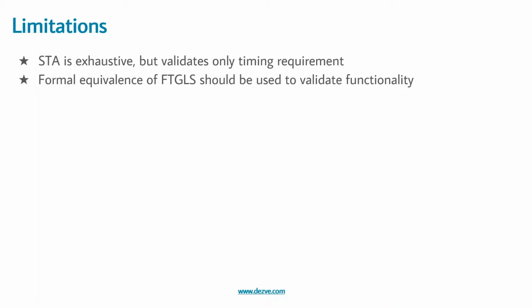Or we might want to run an entire test case, gate level simulations, correct? But running gate level simulations takes a longer time, and what if we have not exercised one particular scenario or test case? It can so happen that the transformation was okay for all the test vectors we had checked, but there was one case in which the RTL and the netlist are not equivalent.